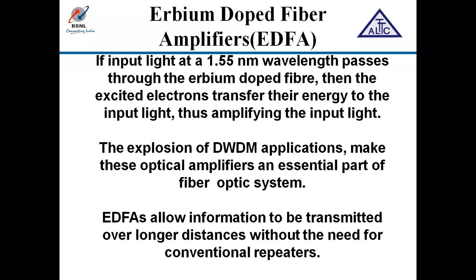If input light of 1550 nanometer wavelength passes through the erbium doped fiber, then the excited electrons transfer energy to the input light, thus amplifying the input light. This is the procedure of how the EDFA works. EDFA allows information to be transmitted over longer distances without the need for a conventional repeater.